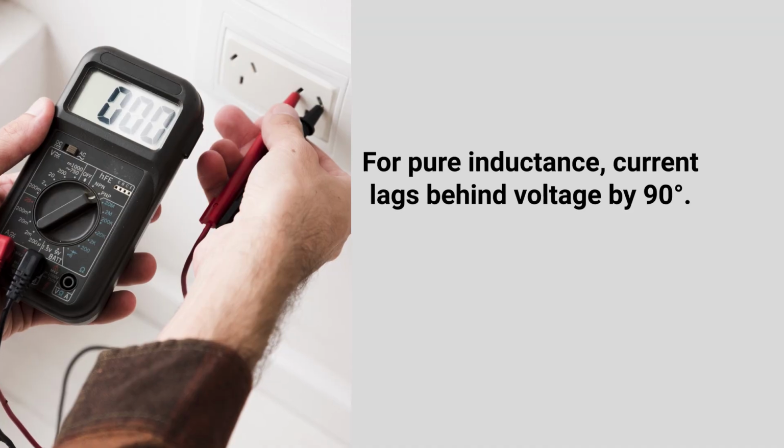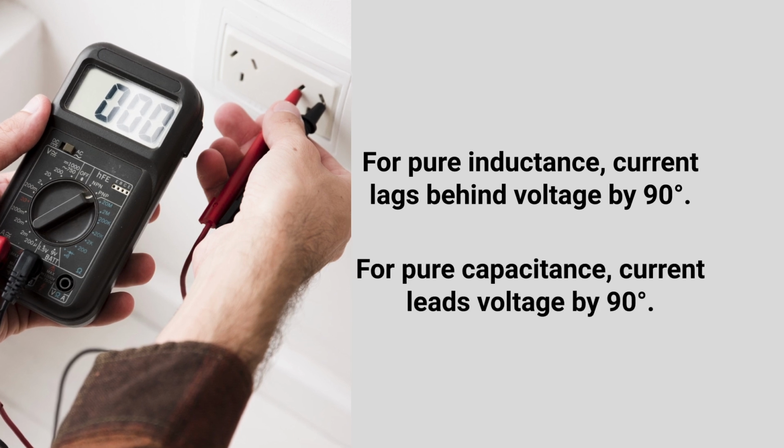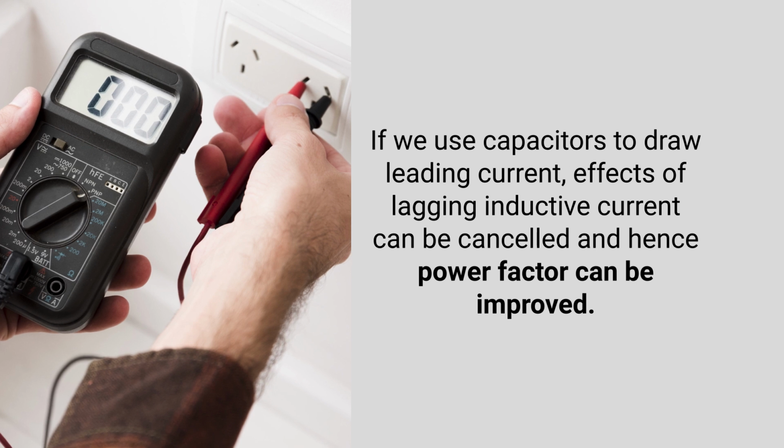So as we discussed, low power factor is mainly due to the lagging current drawn by the inductive load. Before we study the schemes of power factor correction, you can note the following points. First, for pure inductance, current lags behind voltage by 90 degrees. And for pure capacitance, current leads voltage by 90 degrees. So the solution is very simple. If we use a capacitor to draw leading current, we can cancel the effect of lagging inductive current, hence we can improve the power factor.